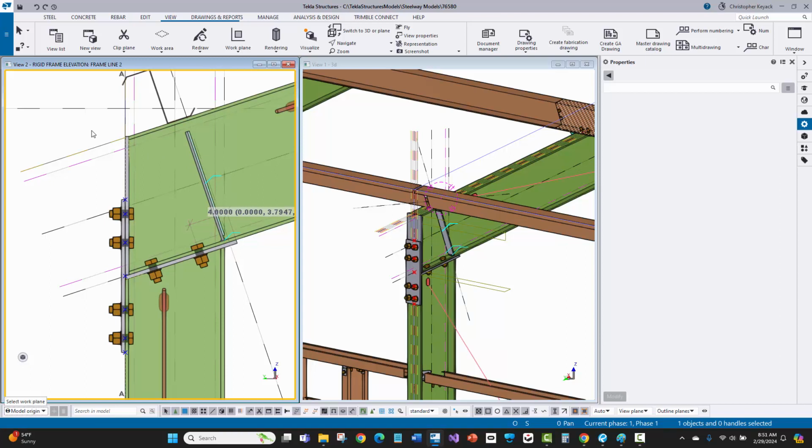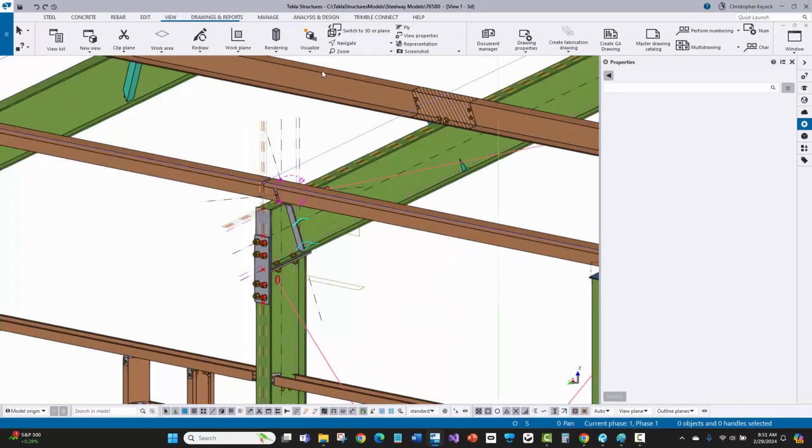Now, when I do the welds here, I'm going to be doing them thinking about this being done on an AGT Beammaster or the robotic welding machine. And so I'm not going to want to actually apply polygon welds here in my 2D view because it'll be modeling them at the center line of the rafter and the column, which will not allow the welds to identify the correct surfaces. So I'm actually going to close this down, and I'm just going to do all of this in 3D.